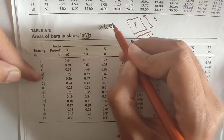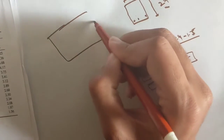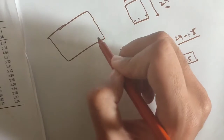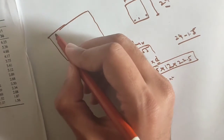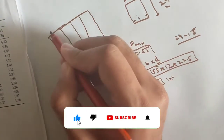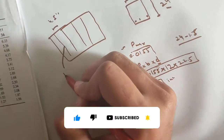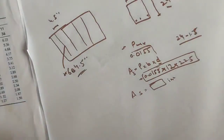For example, it's your slab, and parallel to this direction you got that 1.18. Then you will say that this is bar number 6 and this is the distance, 4.5 inches. So it's very simple, but at the end of the day you should have knowledge about this.